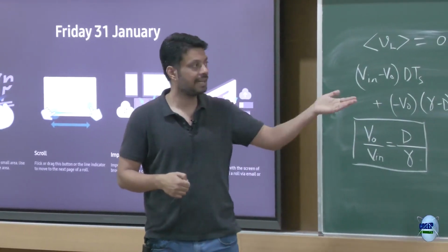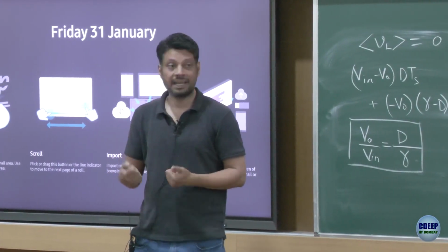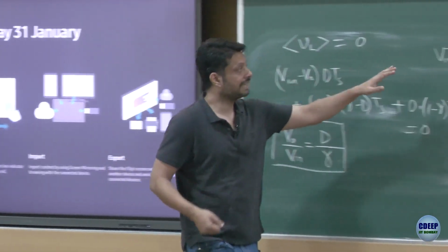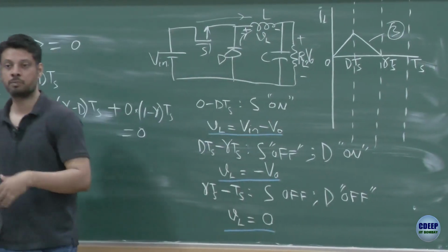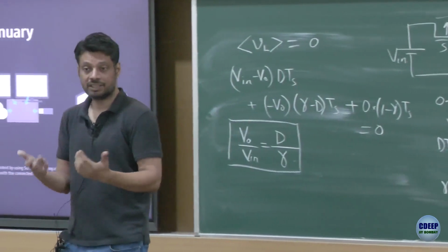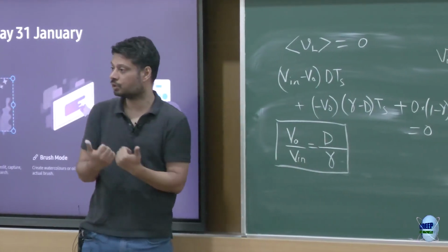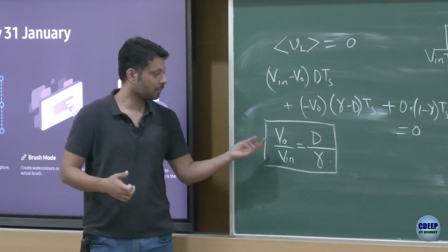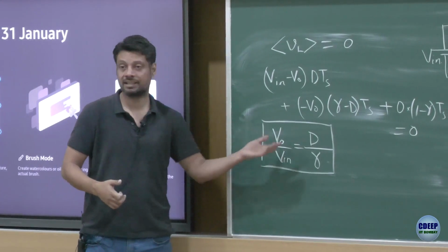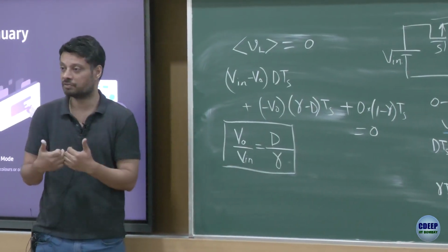And therefore, in reality, all these converters have to have a closed loop kind of operation, where the duty cycle gets adjusted based on observation of the output voltage, right. So if you see the output voltage becoming 60, you adjust the duty cycle. The relationship is still the same: if you reduce the duty, the output voltage comes down, thank God, that doesn't change. So it's still the same relationship, but the factors will keep on changing. So if your output voltage goes to 60, you bring it down to 50, right.